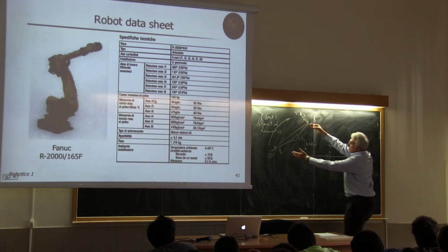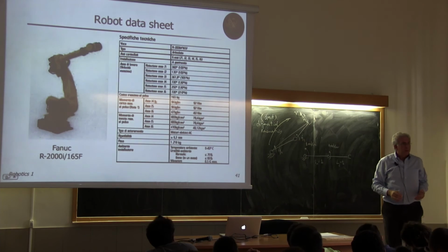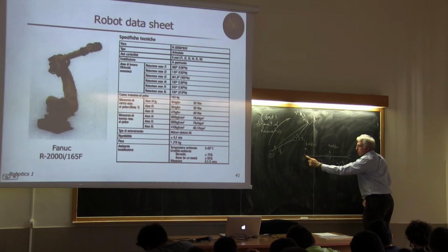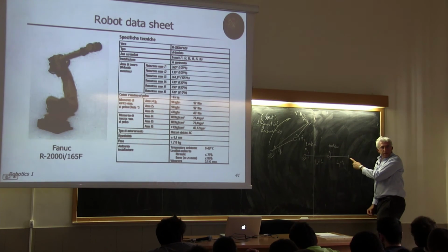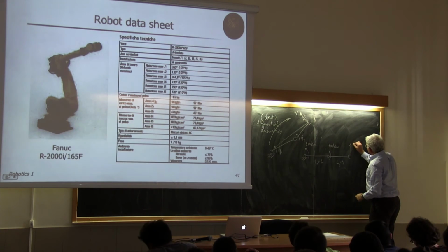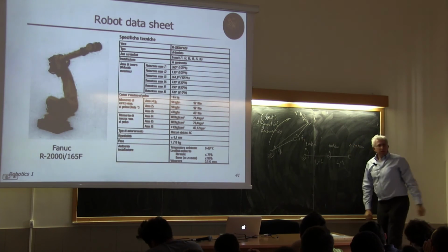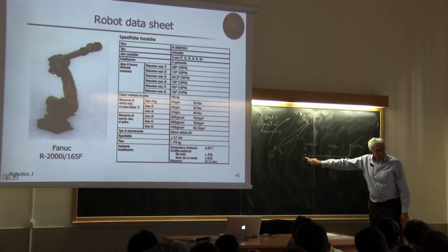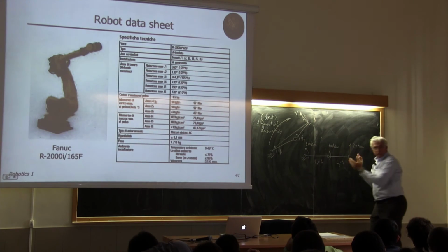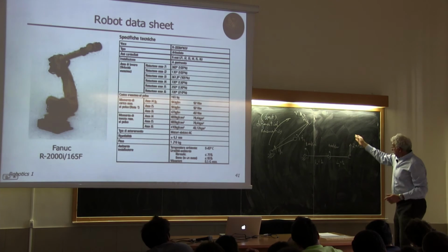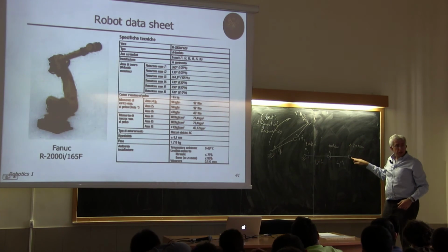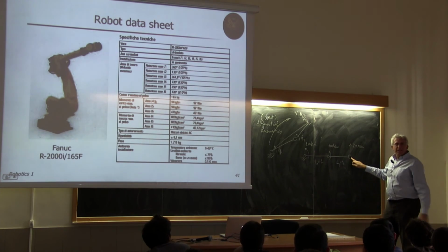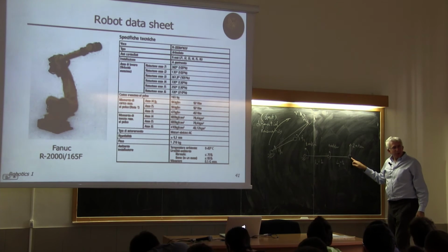Well, we do exactly the same computation. Now we have numbers. Okay, so let's look at the contribution of this velocity. This is 1 radian per second at the distance of 2 meters. It will give here 2 meters per second speed. Angular velocity times distance. And it's in this direction because it's the normal to the segment between these two points.